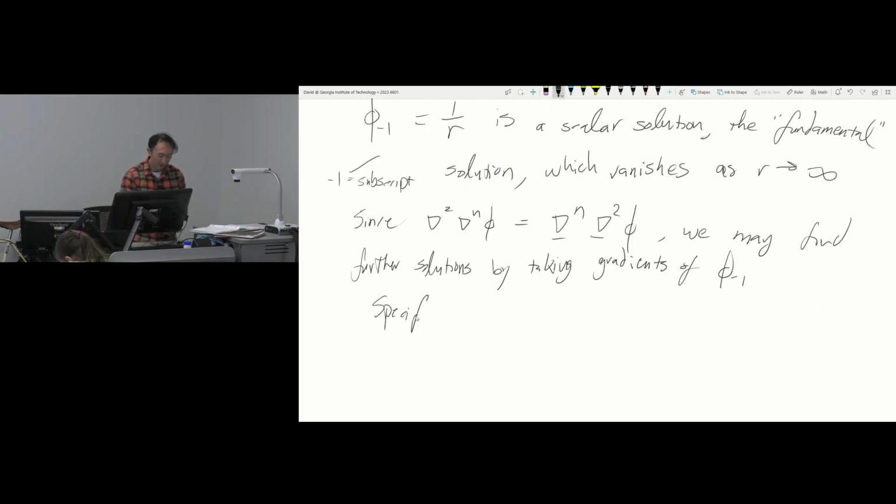And a lot of fluid dynamics is done on spheres because the math is tractable. So what I'm writing here is not really ad hoc because you get to use this for a lot of different problems. For example, if the Laplacian of phi is 0, then I can just take the gradient of phi. As you know, the gradient is a vector. So when you take the gradient of a scalar, you increase the order, going from a scalar to a vector to a tensor. So for example, if I take the gradient of phi, which was a scalar, that becomes this.